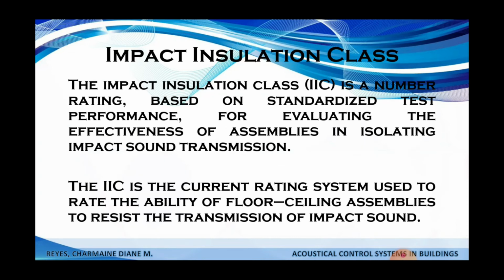Impact insulation class. The impact insulation class or IIC is a number rating based on standardized test performance for evaluating the effectiveness of assemblies in isolating impact sound transmission. So yung IIC is an acoustic rating na ginagamit para ma-quantify yung impact ng sound absorption and vibration isolation. So ito ginagamit to sa mga floor at saka sa ceiling assemblies.